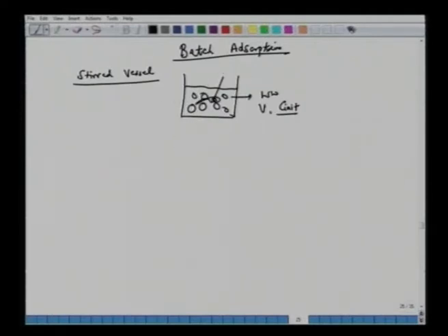There is a little bit of stirring here, so that the concentration inside is well mixed, but not to the extent that the mass transfer coefficient at the interface is very large. So let's get back to this. We have volume, certain initial concentration C, and certain adsorbents. Let's say particle size is dp, total weight is W, and we know its external surface area, in square meters per gram. This is known to us.